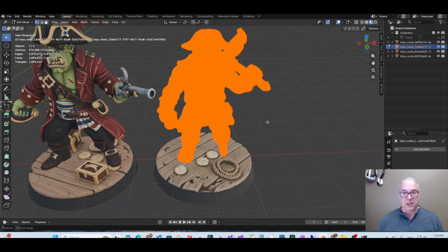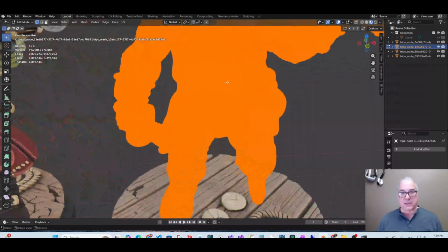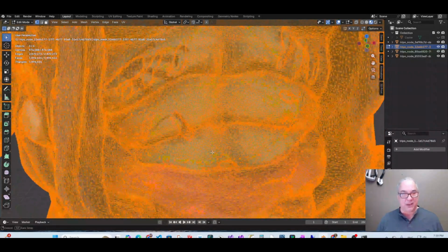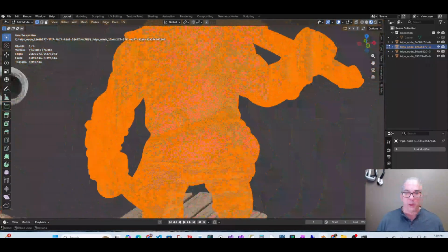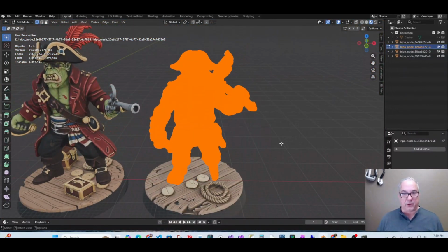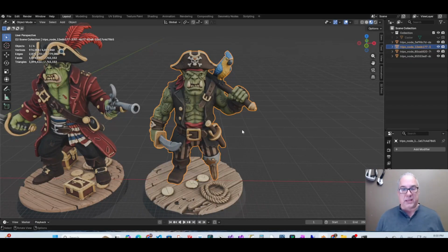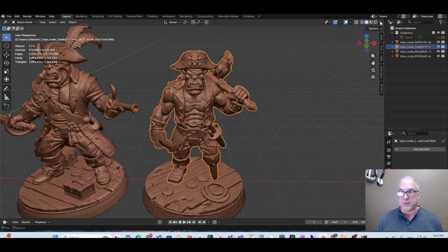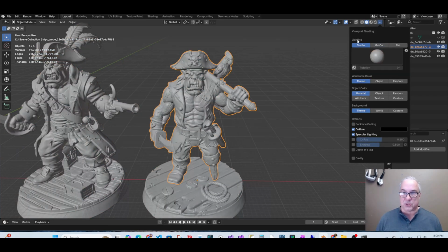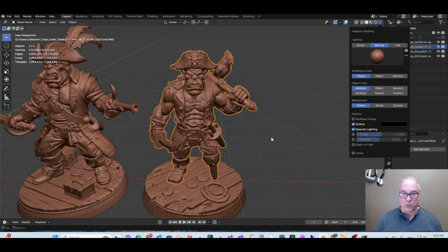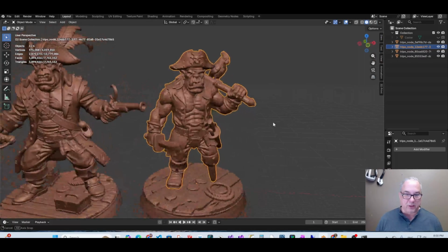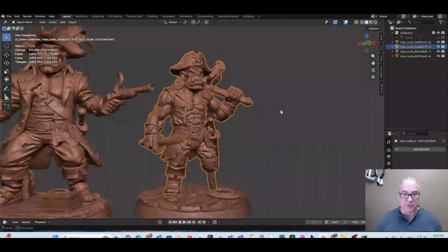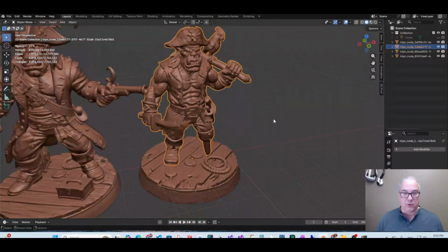As you can see, the number of dots that he is made up of is insane. He's roughly 2 million polygons, which my printer can handle. I can print that, but there's no need to save out a model this big. Right now I'm in textured mode. I'm going to go into flat shaded, and what I've got here is a matte cap material. If you click this drop down, normally you'd be in studio. I come over to matte cap and use this clay colored texture because that gives you a nice view of all the physical detail of the geometry. I think that's really nice.